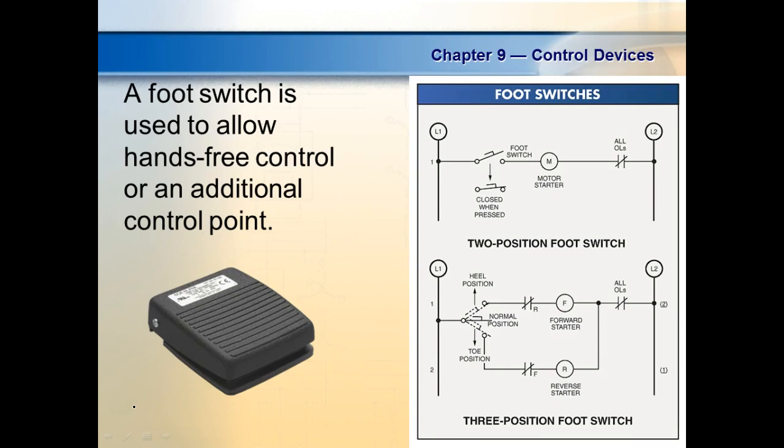So I could rewire it to run always in forward, I could rewire it to run always in reverse, or I could bring those wires out and then I can control when the motor goes into reverse or forward. We do that with either a switch or something. Later on we'll do it with relays. We'll look at a forward reverse control circuit with relays. And I don't know if we got one wired up. We got one on the PLC.